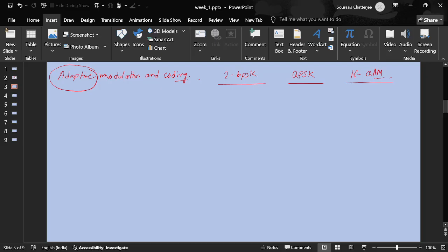The symbol will be different. Like BPSK will have the least one. 16 QAM's points will be different. Okay, so if I look at BPSK, what are my two options? It will be zeros or ones, only one bit per symbol. Yeah, so here you can transmit 1 bit per symbol, because you only have two choices to choose from.